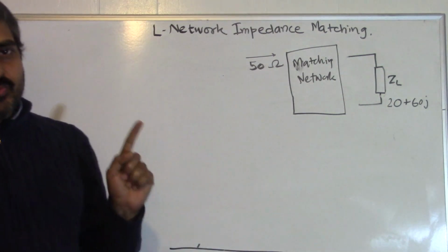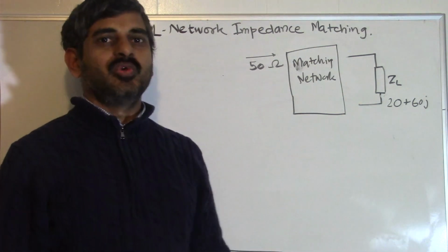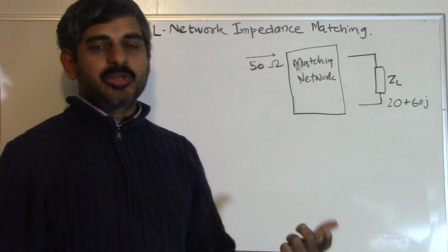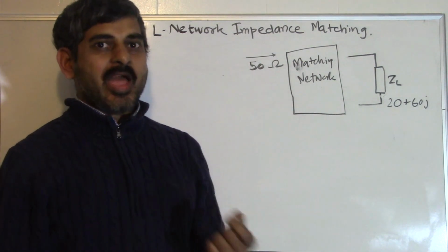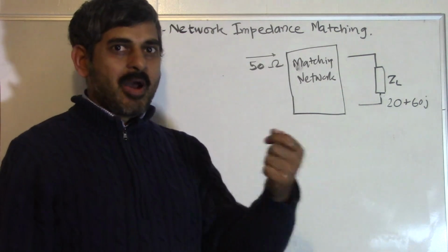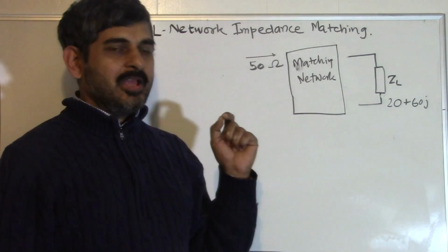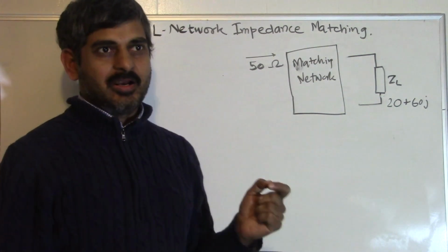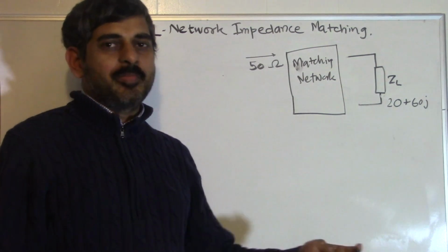Anytime you introduce a resistor, any current flowing through it will have an ohmic IR drop that will be lost. If you have a reactive element, there will be an instantaneous power drop, but over one complete cycle of either a capacitor or an inductor, the net power drop is zero.